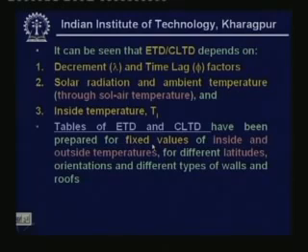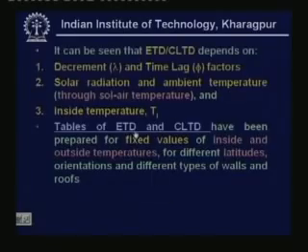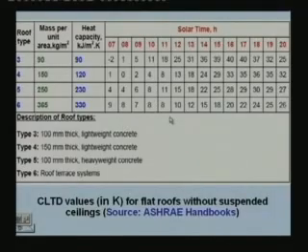And tables of ETD and CLTD have been prepared for fixed values of inside and outside temperatures. For example, they are available in ASHRAE handbooks for different latitudes, orientations and different types of walls and roofs. So let me show typical tables. So this is the CLTD table for a flat roof without suspended ceilings, and this is taken from ASHRAE